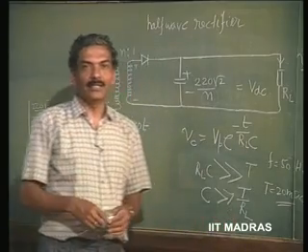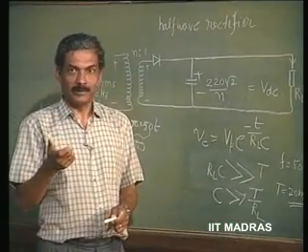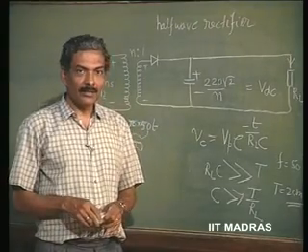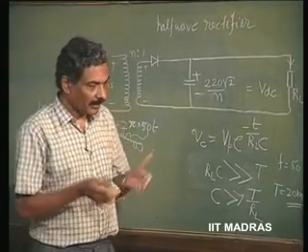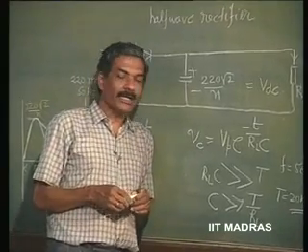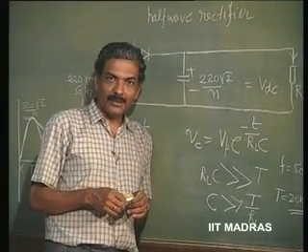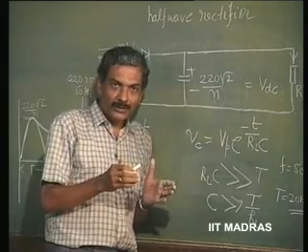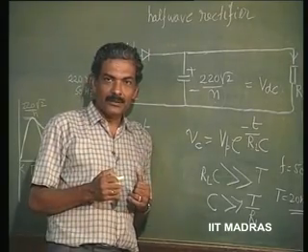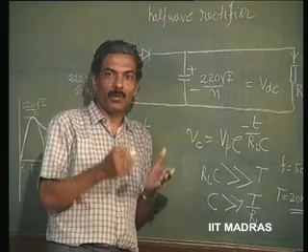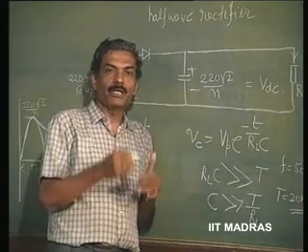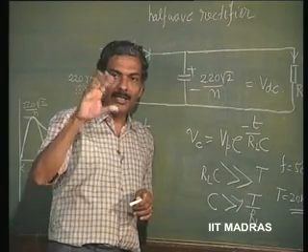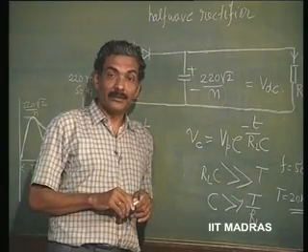Your radio receiver under full volume, giving maximum power to your loudspeaker, is going to need some amount of current, let us say 100 milliamperes, and the voltage needed is 12 volts. Then 12 volts divided by 100 milliamperes, which is 12 volts divided by 0.1 ampere, means 120 ohms is the load resistance that the radio is going to represent.